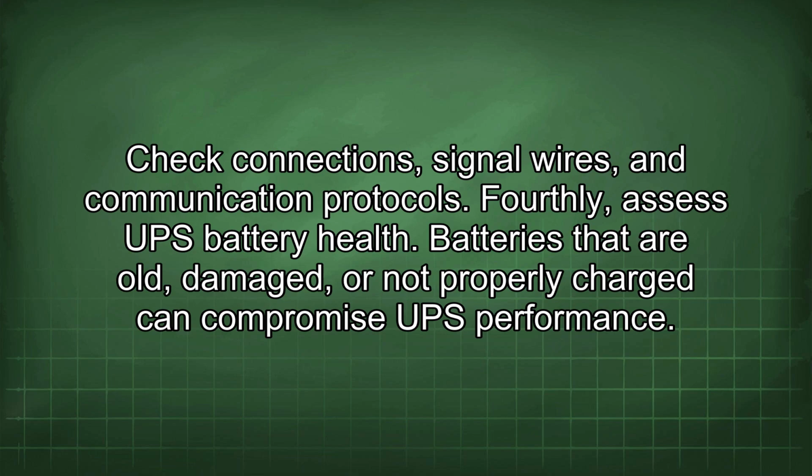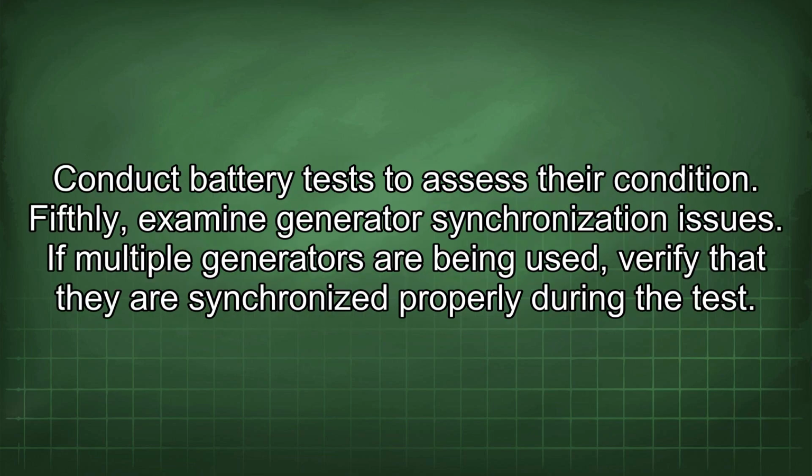Fourthly, assess UPS battery health. Batteries that are old, damaged, or not properly charged can compromise UPS performance. Conduct battery tests to assess their condition.